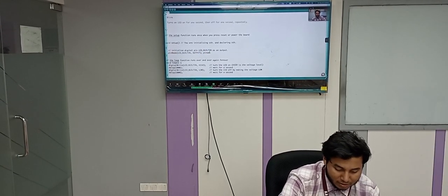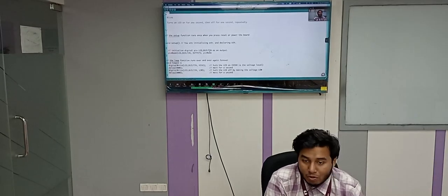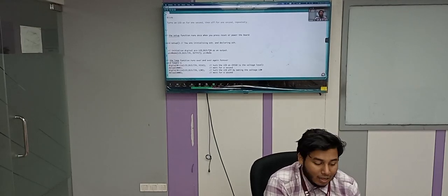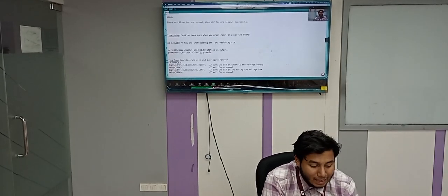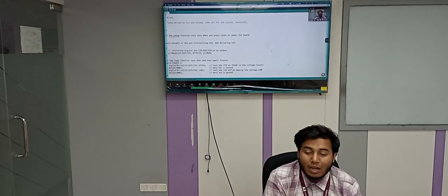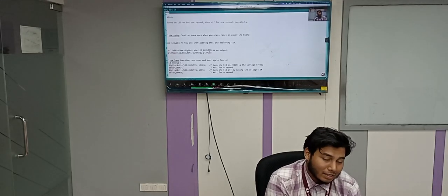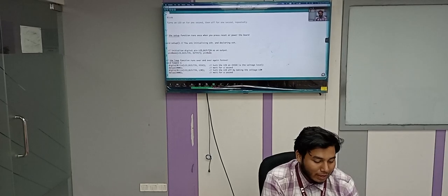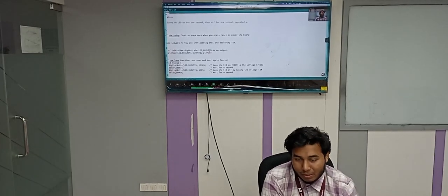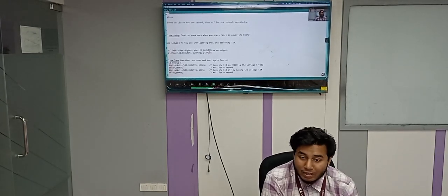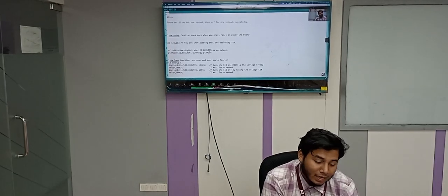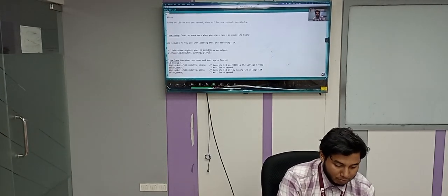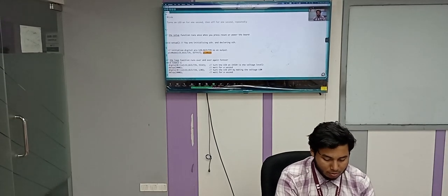If you make this M a capital M, then the color changes. It indicates that, okay, fine, there's a mode of the pin, like digital or analog or something. And it could be input or output. So there are different modes. To declare whether it is an input pin or an output pin, you have to declare the pin mode. And there are two portions of pinMode. What?